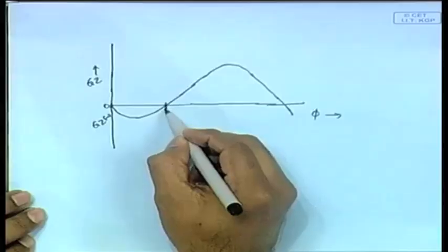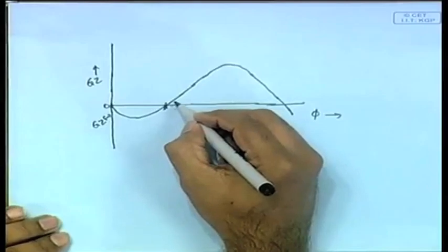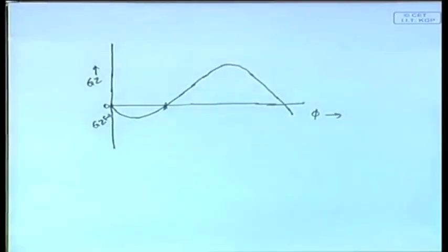Now some small factor, let us say a wind came, it heeled like this. Now what will happen? The righting moment itself is going to cause it to heel. So it will continue to heel till it reaches here. At that point, when it reaches there, any more heeling, the righting moment is positive after that. So after that it will tend to come back.